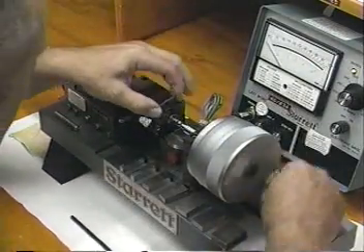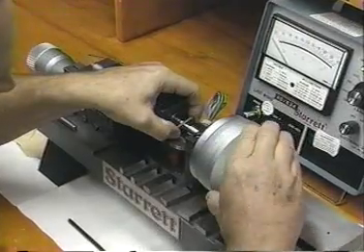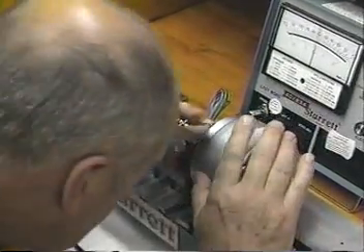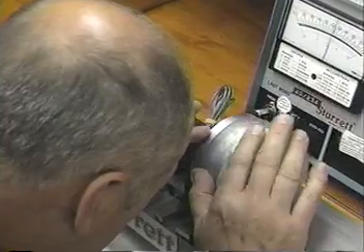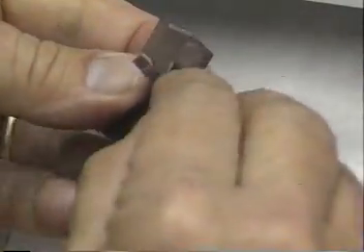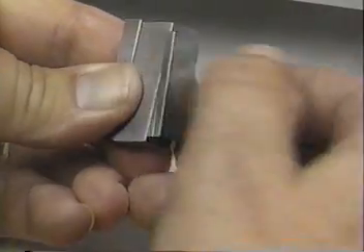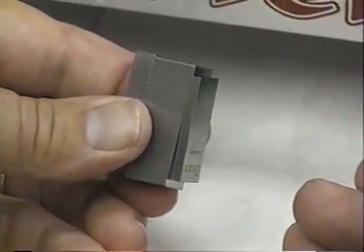Because of their high degree of accuracy, gauge blocks are invaluable in calibrating precision measuring tools, instruments, and gauges. In order to obtain the proper length, blocks of different lengths are rung together. The blocks adhere, as though magnetized, to form a highly accurate stack of blocks.